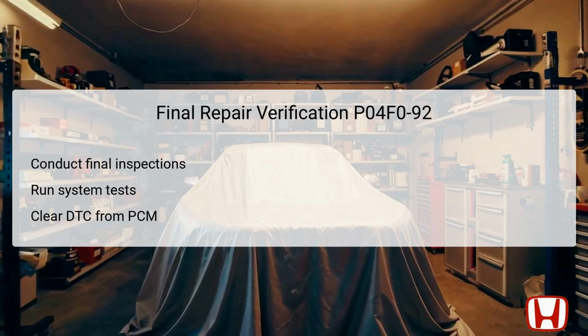Upon completion of all necessary repairs on components related to DTC P04F0-92, the final verification step is essential to ensure everything is functioning correctly. Begin by conducting final inspections of all components involved, including the EVAP canister, purge valves, and associated piping. Next, run the appropriate system tests through the HDS to confirm that the repairs have resolved the issue. Finally, clear the DTC from the PCM to reset the system.